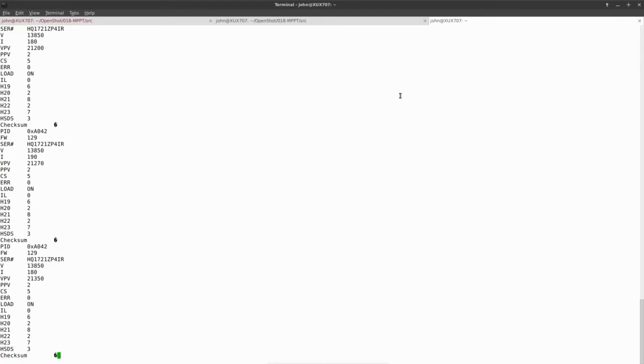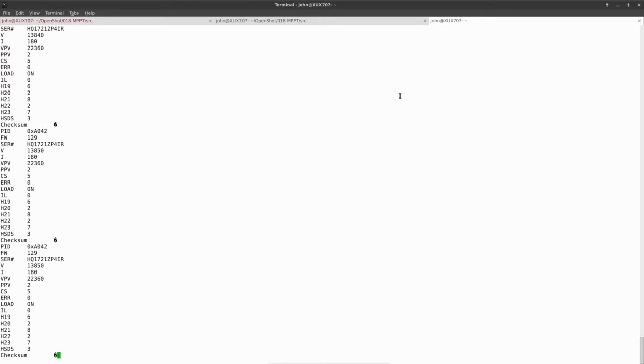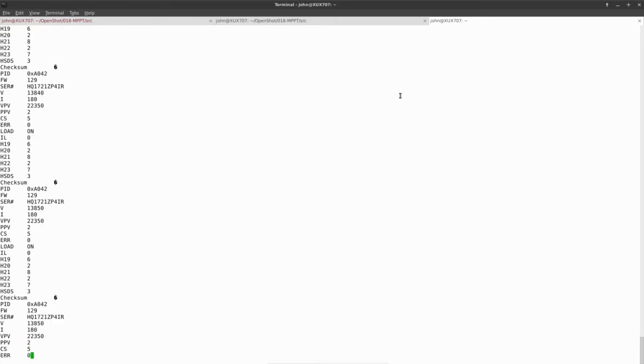So now you can see the protocol as it's documented there. It's spitting out a record pretty much every second, and that is obviously ASCII readable text because it's human readable. Now I haven't got into the other protocol, but the other protocol in here is a hexadecimal based protocol, which is not human readable.